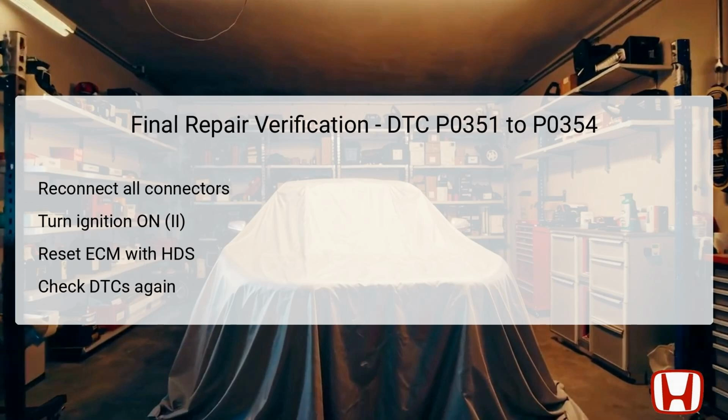If DTCs P0351, P0352, P0353, or P0354 reappear, this indicates ongoing issues that necessitate further investigation, particularly focusing on poor connections or substituting the ECM if needed. If no DTCs are present, the troubleshooting and repair process can be considered complete.